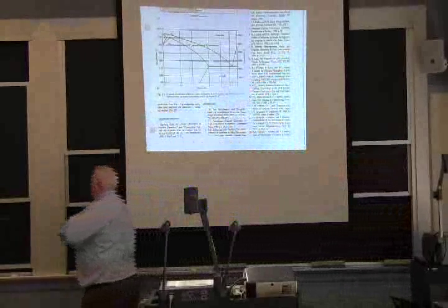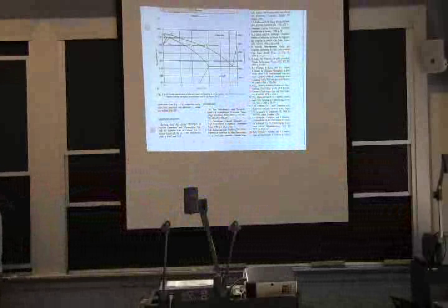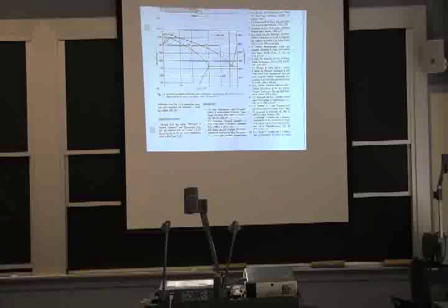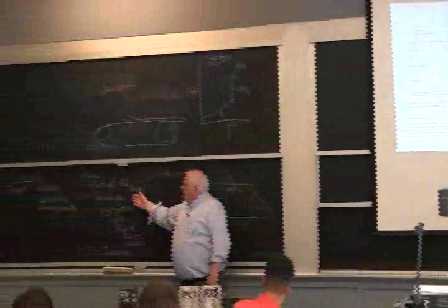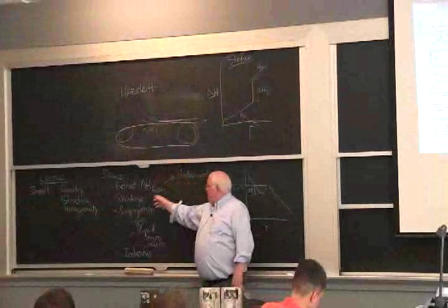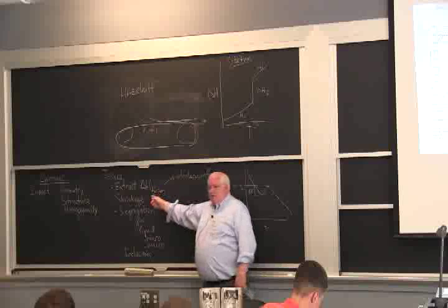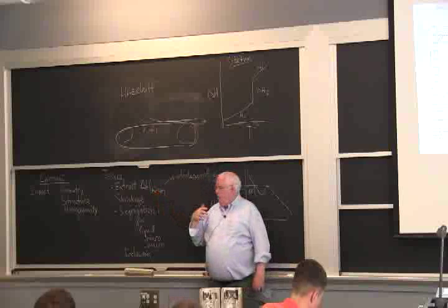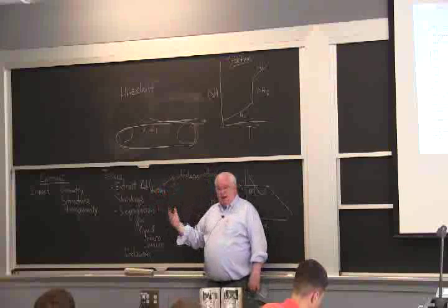So if I go back and look at my challenges and the issues, we've talked about shrinkage and how we can do continuous casting or use risers or chill blocks. We've talked about extracting the heat of fusion, and if you've got really big things, you have to wait hours or days. We get down to very thin things, and we'll talk about rapid solidification, where we melt things and freeze them at 1,000,000 degrees per second.